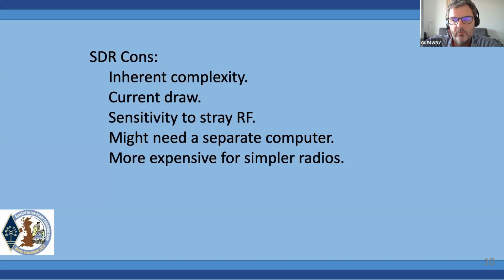And people won't understand a word of what you're saying, and you're just going to be transmitting an incoherent signal, if I can call it that. Or for Morse code, using CW, your key might just go crazy, basically. And that does happen, and it's due, of course, to this inherent complexity of SDR radios. The more components you add and the more integrated circuits, the more chances that stray RF current can affect them in a negative way. Never in a positive way, anyway.